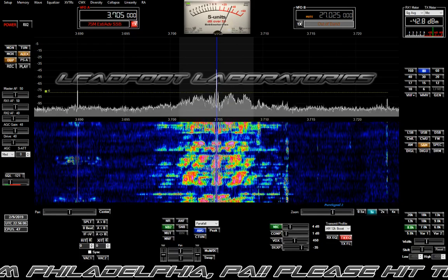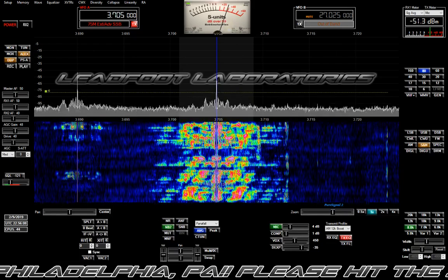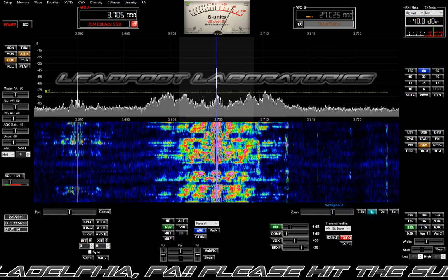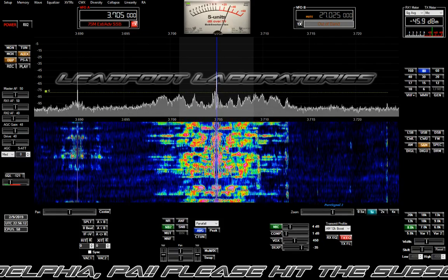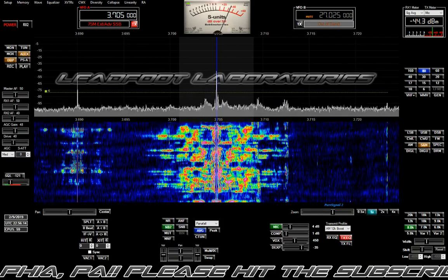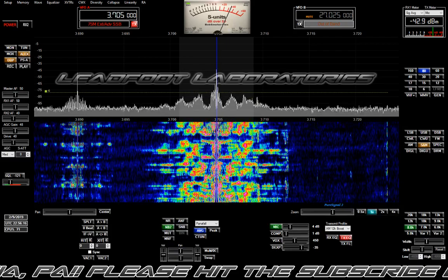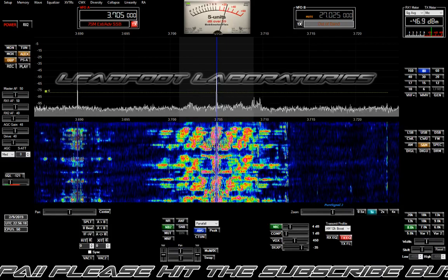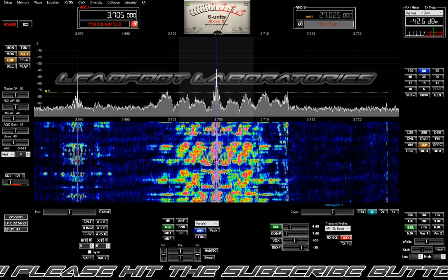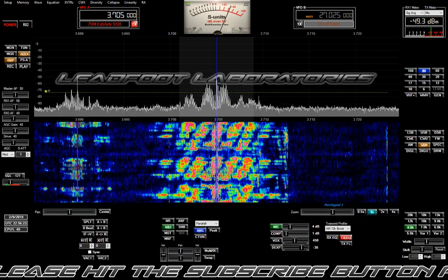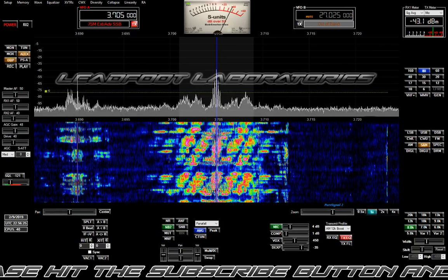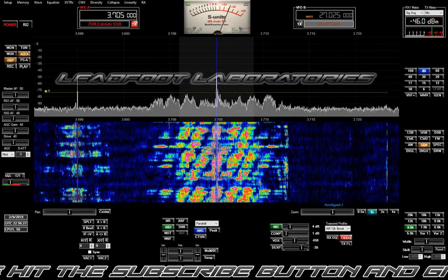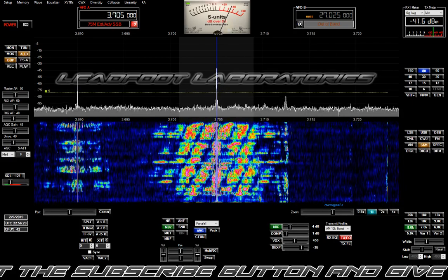And what that transmitter actually was, it wasn't a brand new transmitter per se. Rather, it used the existing 50 kilowatt transmitter that they had, which I think was an RCA. And it was driven, of course, by that 50 kilowatt RCA, had 10 dB of power gain, had its own external plate modulator.